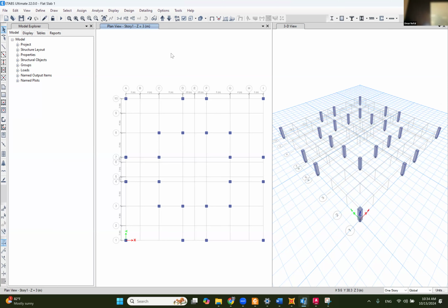To draw a shear wall, look at these. These are the things that you would draw the shear wall with. They are activated now. Look when I click on the 3D, what is gonna happen to them? They are deactivated. So to draw them, you have to be in the 2D. Okay, so right now I'm activating the 2D and I'm gonna click, there's something called quick draw walls.